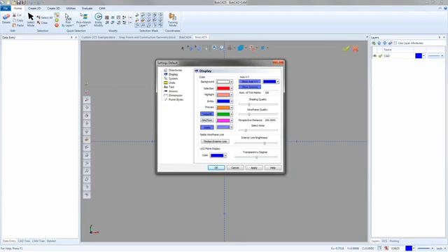We don't run full graphical capabilities all the time because that would just be a major strain on your system. So what we have is just the shading and wireframe quality. This is just set about a quarter of the way up right now. That's our default. And if you bring it to the right, it's going to boost the quality. It's going to make everything look better. But there's a drawback to that. When things start looking better, it can slow down how long it takes to load. You know, when you're doing a rotate, it could potentially take a little bit longer.